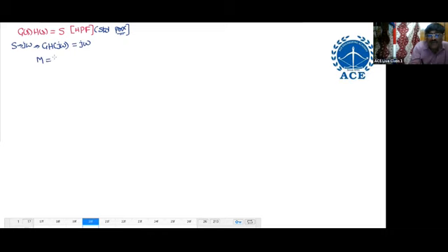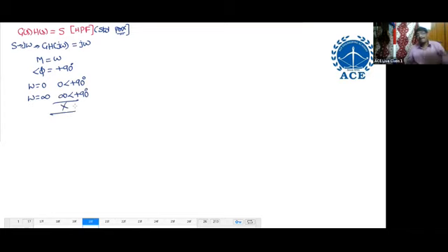Magnitude equals omega, phase angle is plus 90. At omega 0, the magnitude is 0, angle plus 90. At omega infinity, the magnitude is infinity, angle plus 90. Our condition is not satisfied, which means standard procedure, nothing extra to do.